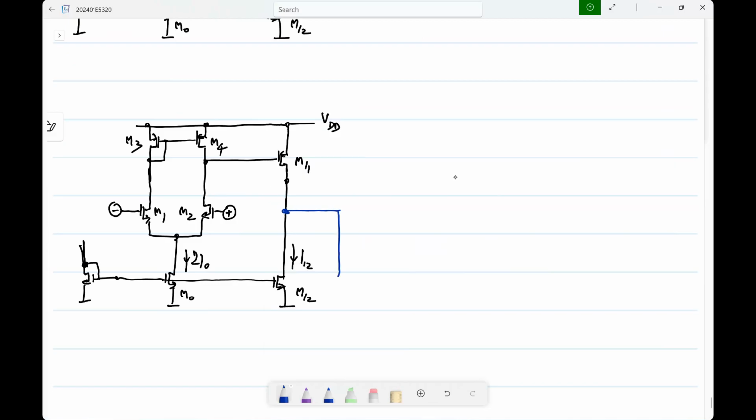So let's say, just for argument's sake, I use an NMOS third stage. I call this M21 and M22, and this bias comes from some current mirror. So the M22 is a current source basically. It is the active load for M21 and it comes from a current mirror.